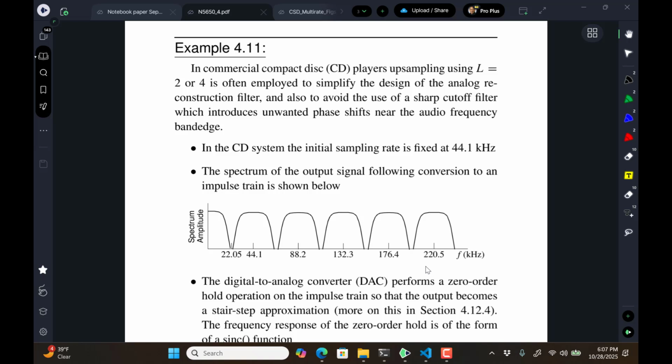Remember? So that it stretched it way out, and then that folded back around and created massive aliasing, right? So we need to cut this down. How do we do that? And we'll talk about that later in this chapter, where we end up with a really high order analog filter to do that. But by the same token, when you go to reconstruct it, and this problem was in the digital analog converter side. This was in the playback side, not the recording side.